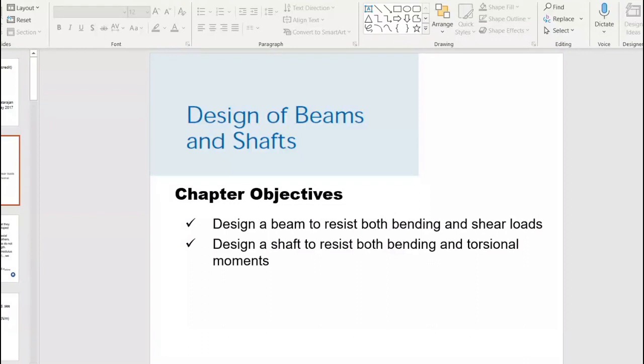I over C is Y. Hence, using the flexure formula, sigma is equal to M Y over I. Later, I will change the notations. It is M Y over I. We can have the formula as section modulus equal to M over sigma. M max is determined from the moment diagram and sigma allowable is specified in a design code.